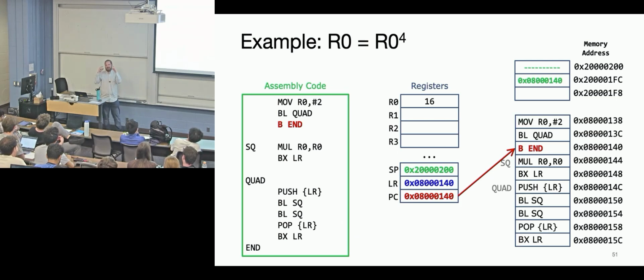The way to rationalize that is how the instruction is made. The instruction does not keep order. The instruction just has 8-bit values, one-hot encoding, and it says you put a bit here for the 8th register or the 7th register, whatever the register number is. So in a 16-bit instruction, there's no encoding of the order. It just goes from, I think, highest to lowest.